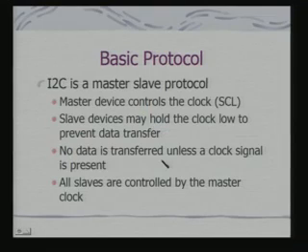So, you have to put pull up resistors to connect these interface lines to the actual supply high voltage, so that they can become operational. Since it is wired AND, the normal state would be high. So, when there is no transmission, it will be high, and if one of these slaves pulls things down, it will be low across the bus.